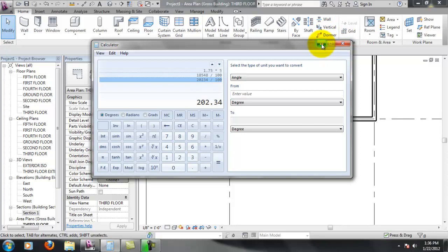I'm going to go ahead and, because we're lenient on the square footage, I'm going to be lenient in this number and say it's an even 200. That way, when I have to bump up, I'm not going to have to bump up because of 2 occupants. So this is the kind of stuff that, like I said, in code class, you're going to learn how to avoid or manipulate. Here, I'm just going to go ahead and automatically, for the sake of this Revit tutorial, bump this number down to 200.